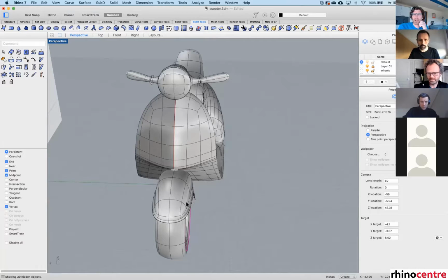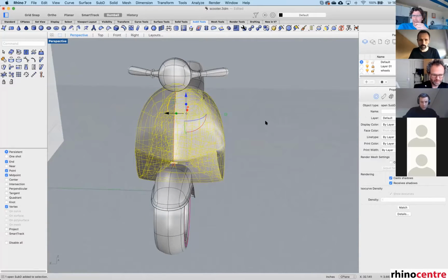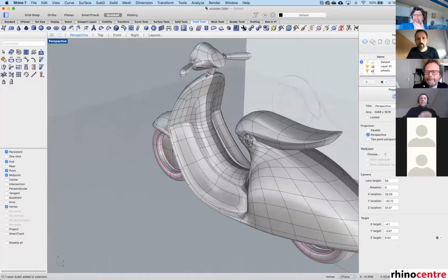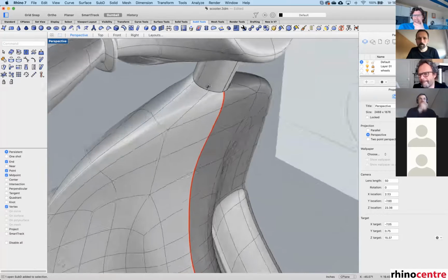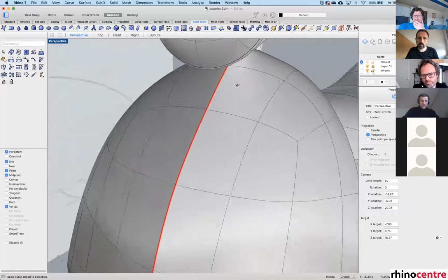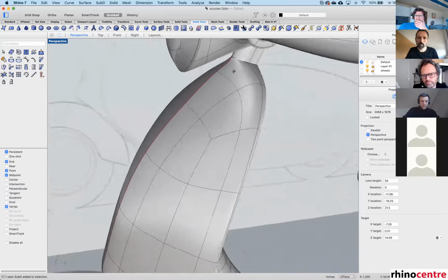Is there something that people would like to see, or if there's a question? Yes, Gijs, why don't you use cutting a hole by the shaft to trim it? Why don't you trim? When trimming, you will automatically convert to Nurbs. So you cannot have trimmed holes in subdivision surfaces. You really need to stay in quad patches as long as possible.